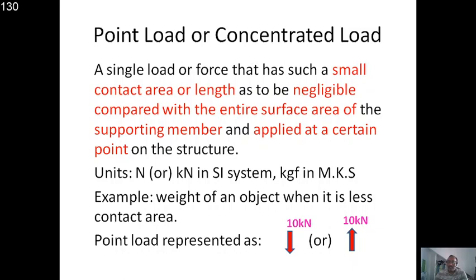If you study it as a phrase, you could not understand this one. So I am breaking this into small words. Whatever terms I highlighted, you just focus on those terms. It is a single load. Whenever I say a point load, it is a single load, or a collinear load, which is a summation of all the loads. And when it contacts an object, it contacts over a small contact area. It is not that a huge area is going to be in contact.